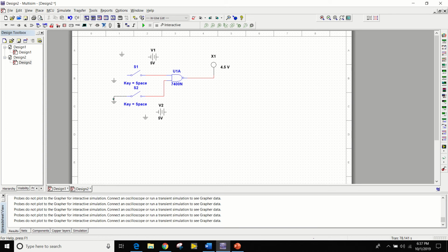So now we'll wire these to ground, this to ground, and this is our minus side of our DC power source to ground, and same over here. Now we need 2 resistors, 330 ohm resistors, your standard when you're working with TTL or LEDs or anything like that.